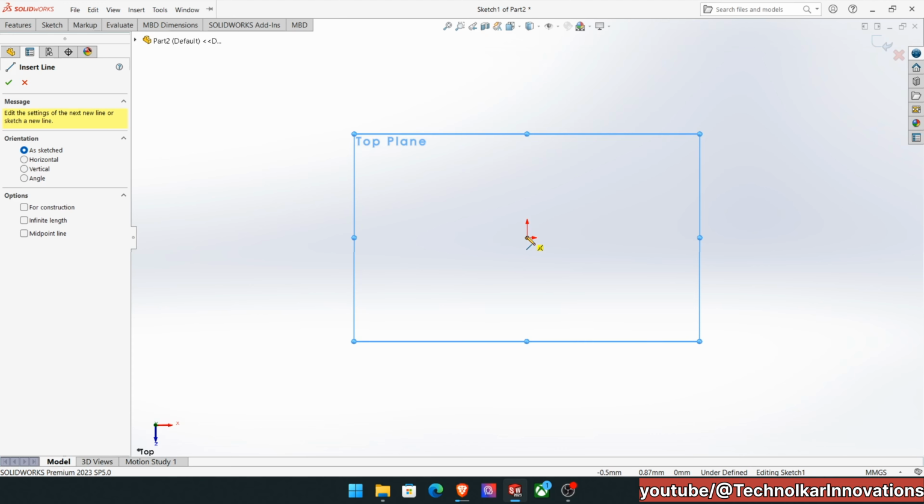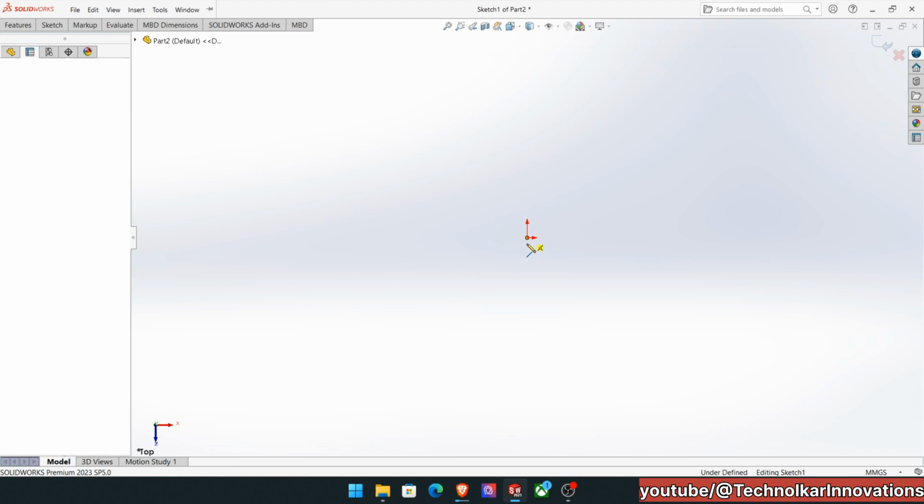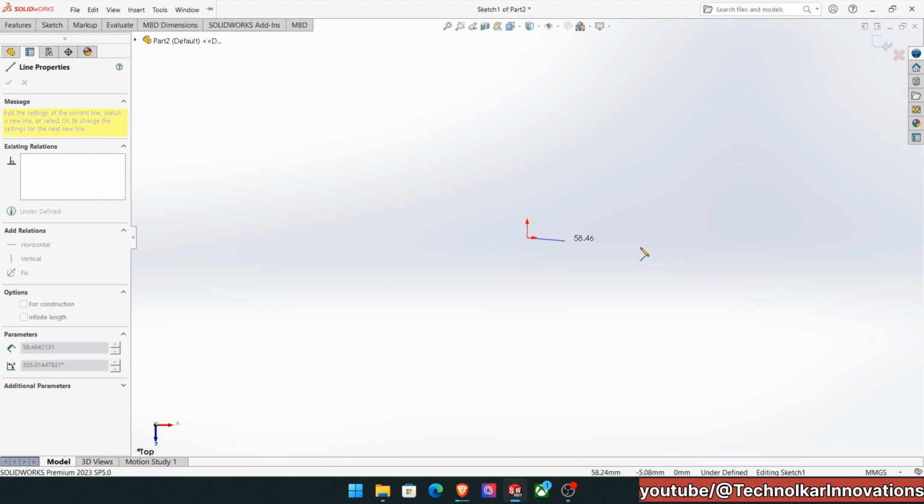So see here, it is exactly at the center. So I will just click on that and I will drag my cursor. When your line is approximately straight, in that relation you can see a dash or a horizontal line. This indicates that your sketch is horizontal, or completely flat. If you want to confirm, you can also confirm with the angle which is showing 180 degrees, and the distance from the center which is showing 105, 110 mm and all.